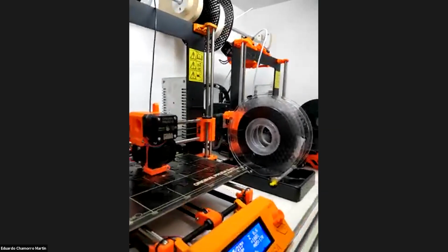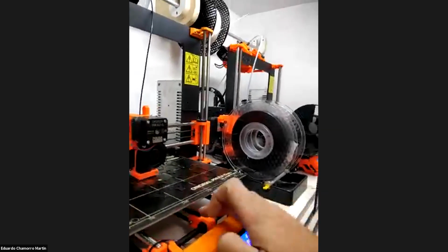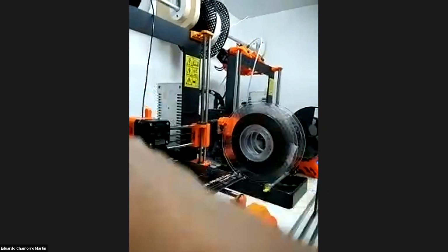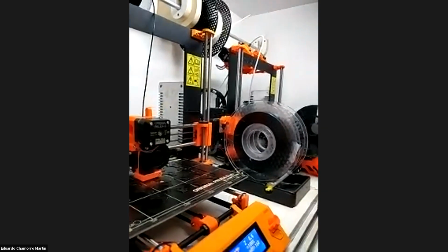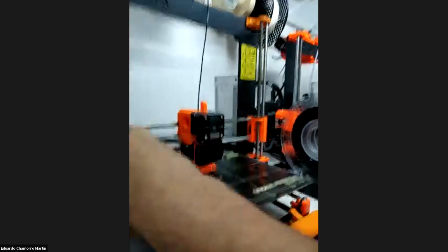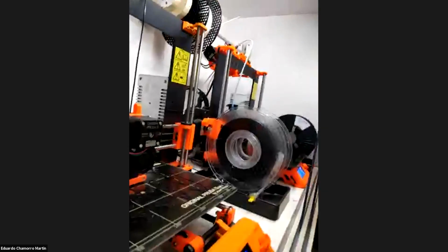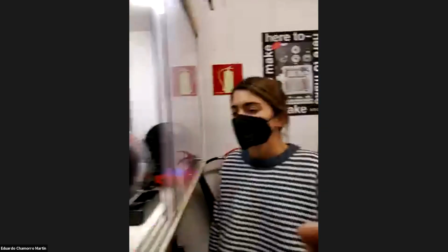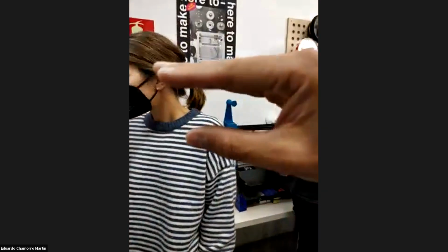With 3D printers, we move X, Y really fast. So we have belts and linear bearings in the X and Y. The Z just moves a little bit every time. That's why we have, again, threaded screws. And here you can see there is only one nut. Actually all 3D printers use this system because it makes it cheap and it doesn't increase the cost a lot. So actually the nut, what would happen?